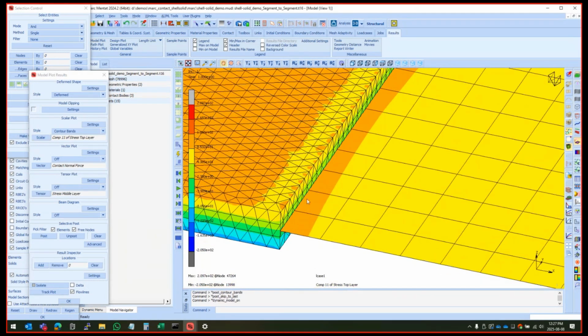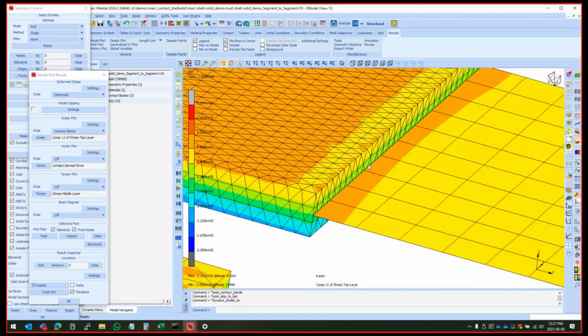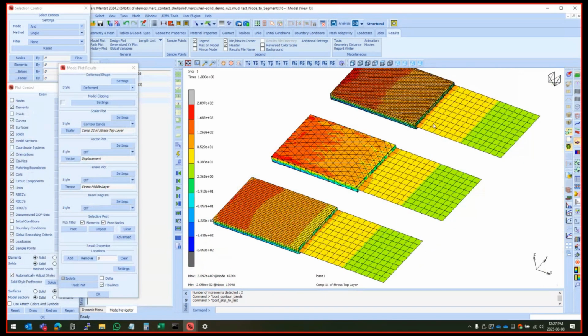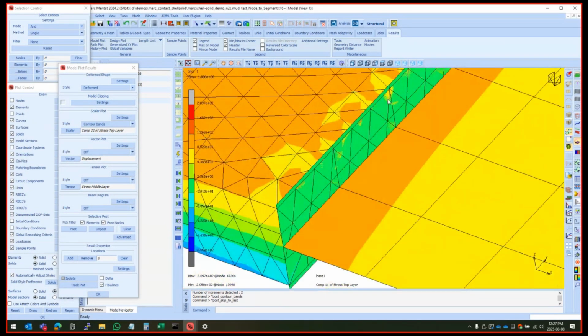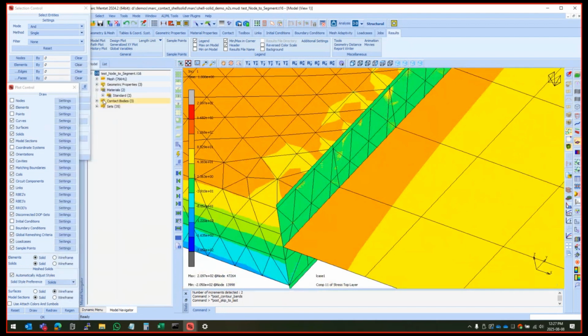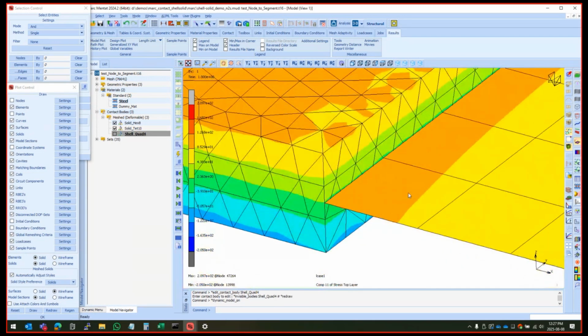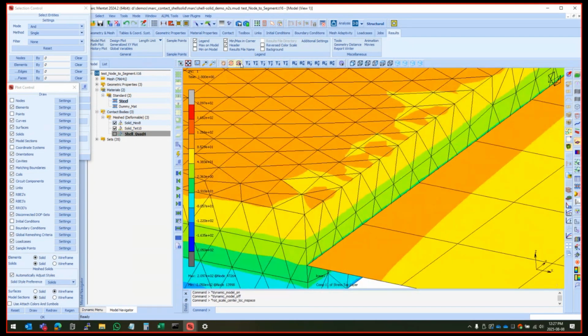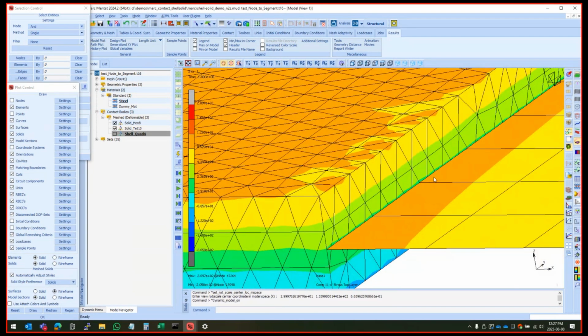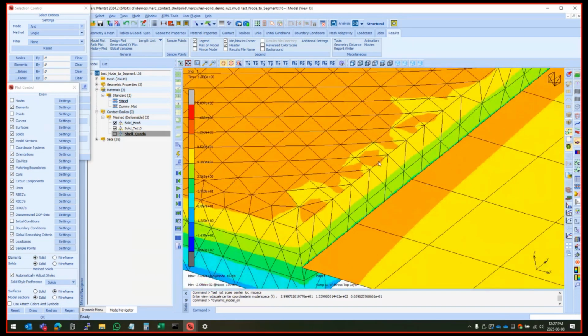Yeah, if I look at that through thickness trace there, that actually looks pretty decent. So at the top, there's a little bit of variation, but through the thickness is nice and linear. This one through the thickness is okay, not perfect. Let's just hide these dummy elements. Yeah, so to be honest, this actually looks okay as well. Not great, but much better than any of the alternatives.